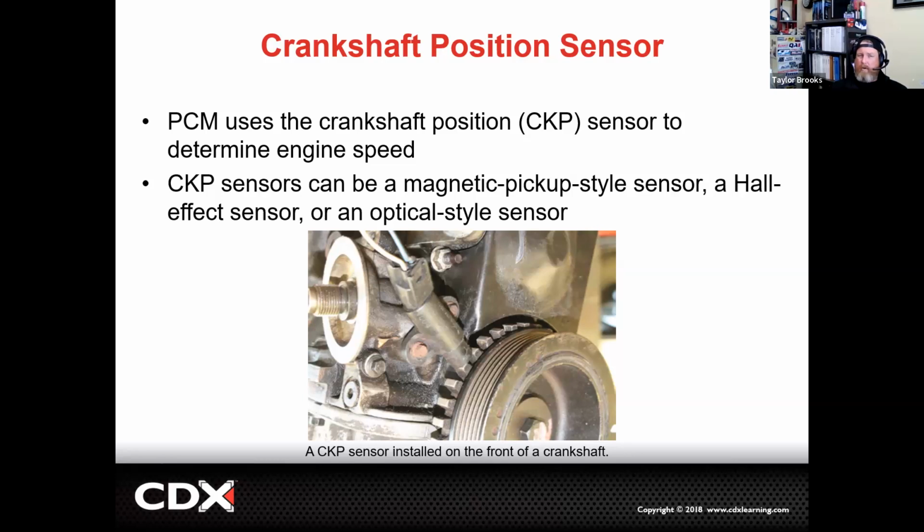It's important to remember that in underdrive gear scenarios where we have a smaller input to a larger output, the PCM will calculate that we are in first gear by looking at the difference in RPM between the engine via the crankshaft position sensor and the output sensor of the transmission. Therefore, it can calculate how much output torque is going down to the ground, and thus we can communicate that over CAN-C to go to the electronic limited slip differential or locker to determine if we do need to limit how much torque is going to the back wheels.